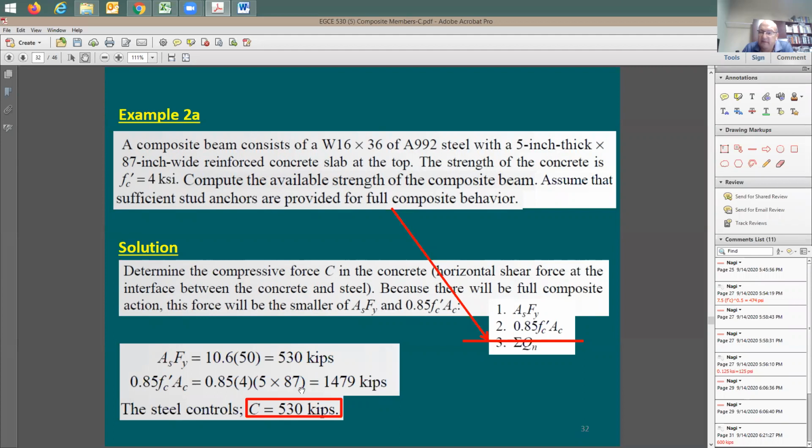Because we consider the full section of concrete that has this stress distributed. The top piece, which is the flange, is going to be concrete, and there is no need for us to transform it into a steel section. We are not interested in finding the moment of inertia. We are not doing elastic stress analysis. This is plastic, so we are doing strength analysis, not stress analysis.